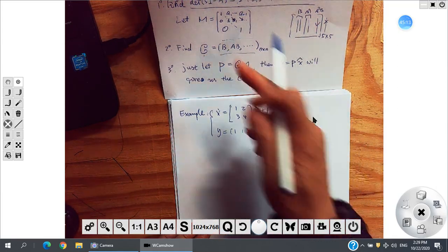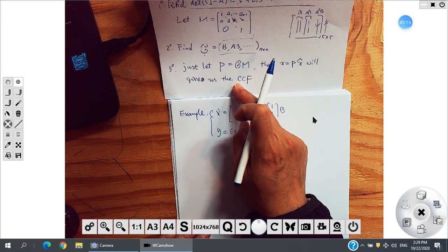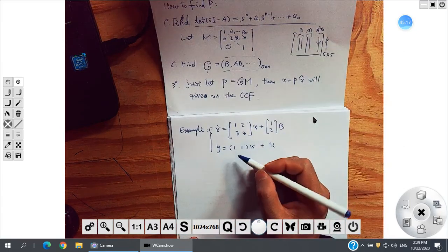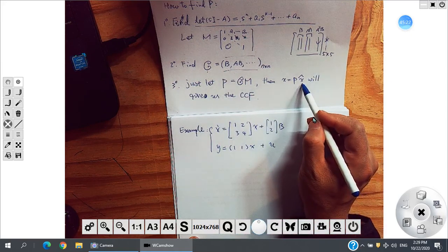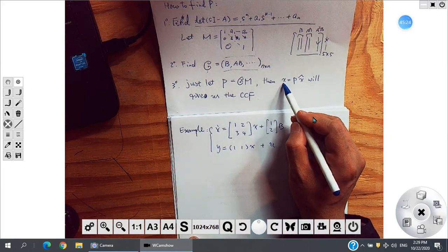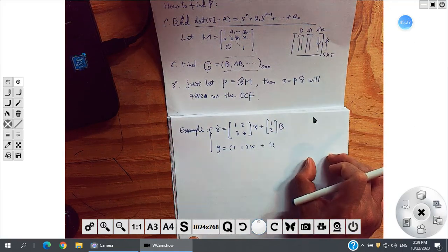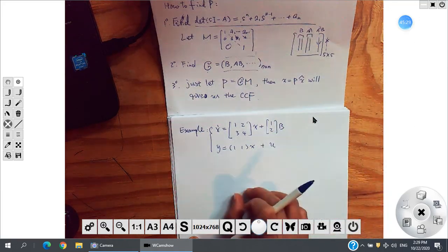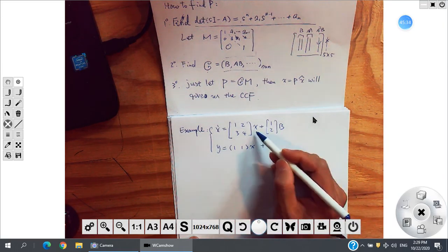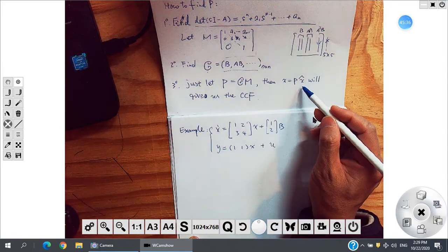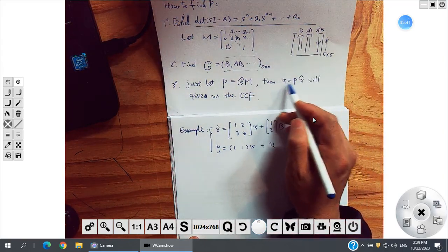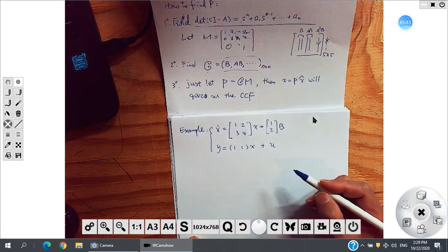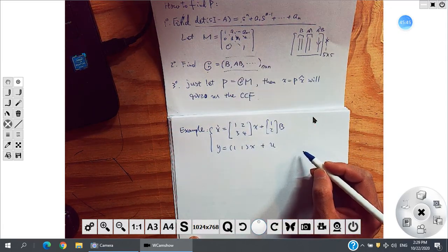But now we try to work in this way, because by this way we can know the new state variable and how to relate it with the original one. If you go to the transfer function and then give the state equation based on it, you lose the relation between x and x hat. If you want to hold this relation between x and x hat, you have to work this way. So now we can work like this.